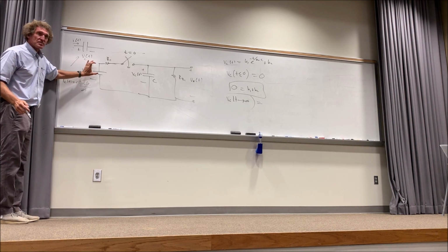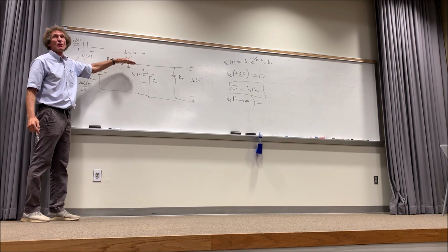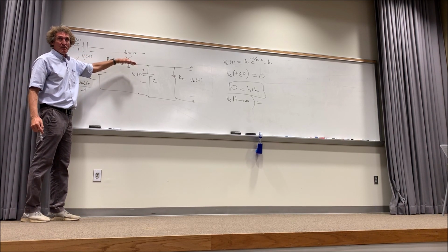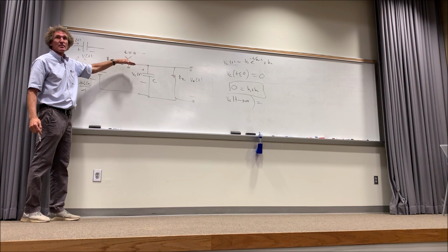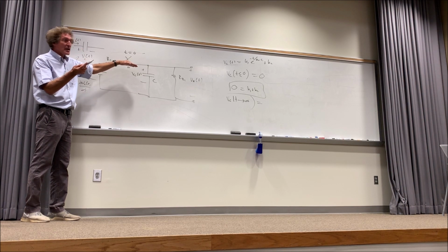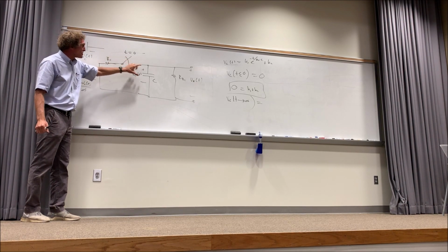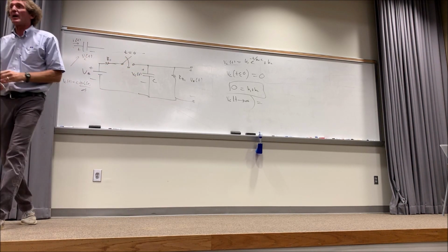That's a DC voltage. Once the switch is closed, the transient mode starts. But as time goes to infinity, for a first order differential equation set to a constant, it's got to go to a constant solution for voltage. How many understand that? How many believe it? You throw the switch, the voltage out here, after enough time goes by, will stabilize.